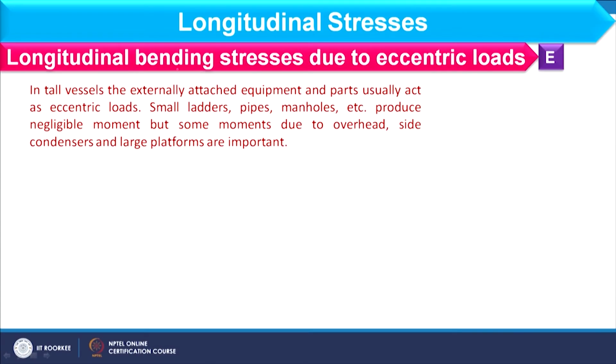So, apart from the dynamic load, we can have other load also, that is due to eccentricity. Okay. So, we consider that as eccentric load, and because of that bending stress is generated in the shell. In a tall vessel, externally attached equipment and parts usually act as eccentric load.